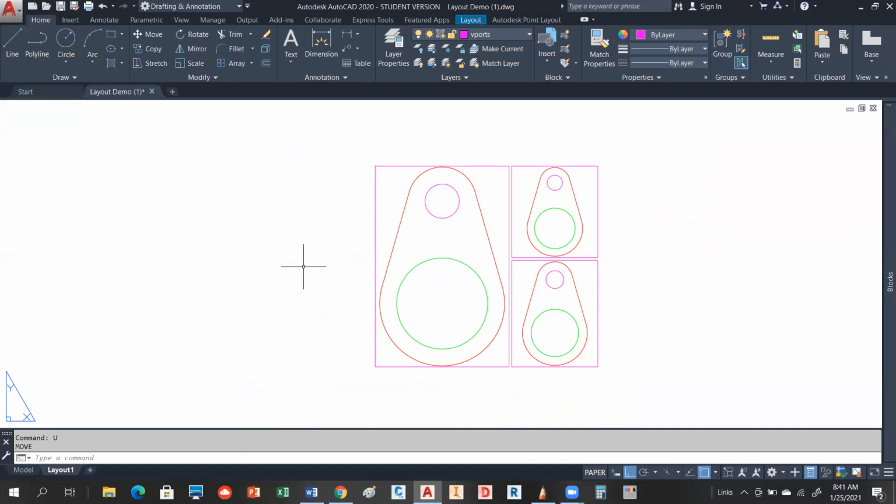When I have real crazy boundaries, particularly surveying type boundaries, a lot of times I'll create an irregular viewport around that because I don't want everything showing up in a rectangle. Especially, let's say I've got contours that are spilling out here. I don't necessarily want those contours to go out there. So I could literally draw a viewport shaped like that and clip it. You can think of those as clipping types of things. Okay, is everybody okay with that?